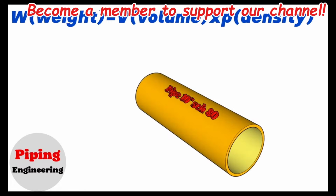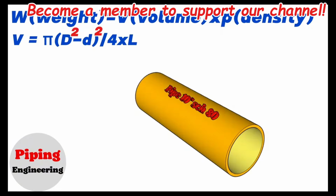To calculate the volume we will use this formula. The volume equals pi multiplied by, in brackets, the squared outside diameter minus the squared inside diameter, divided by 4, multiplied by the length of the pipe. This formula applies to all pipe sizes. We will be explaining the calculations in this video on 10-inch and 16-inch pipe examples. Let's calculate the weight of a 10-inch pipe with a thickness of schedule 80 and a length of 2 meters.